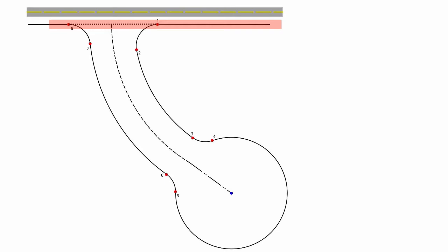since the angle to the center of the curve from either the start or end of the curve is always 90 degrees from the curve's tangent. Measuring the radius distance of 150 feet from the center of the road along the road right-of-way will locate the center of the large curve. This is the center for both curve 2 to 3 and curve 6 to 7.